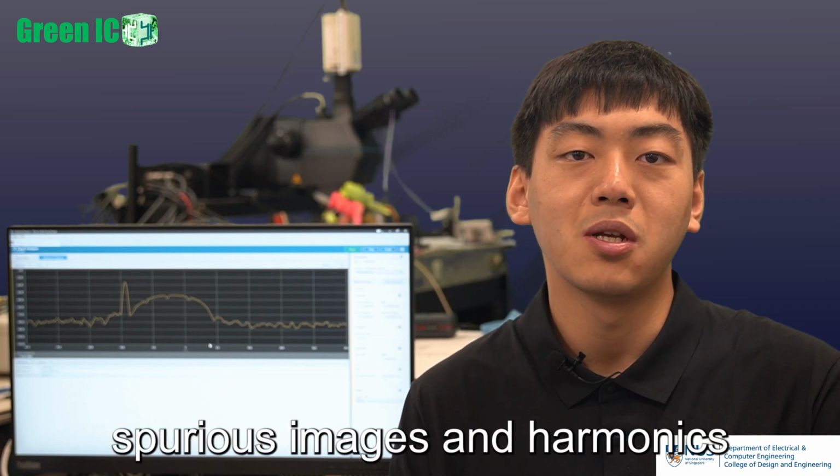Unfortunately, backscatter transmitters traditionally suffer from spurious images and harmonics, polluting the frequency spectrum and degrading the overall wireless channel utilization. Our work proposed to improve the image rejection ratio through quadrature modulation and to partially improve HR by intermediate frequency overclocking to push the harmonics out of the band, though costing more power and limiting channel selection. Even in this case, the harmonics are not mitigated due to the discontinuous phase in modulations used in Wi-Fi 802.11b.